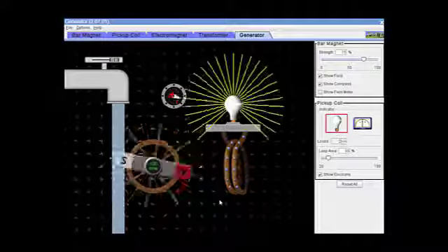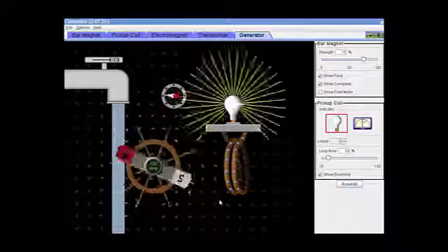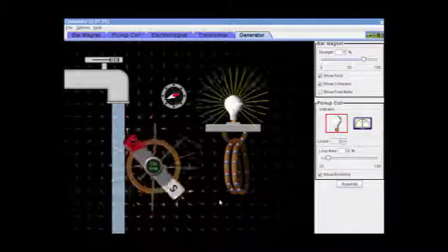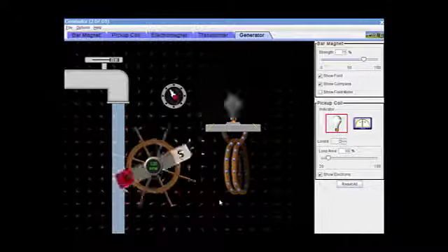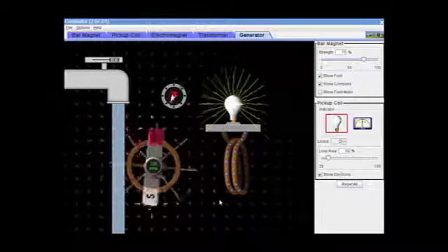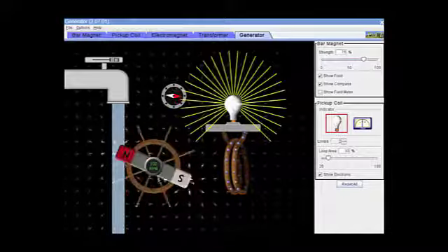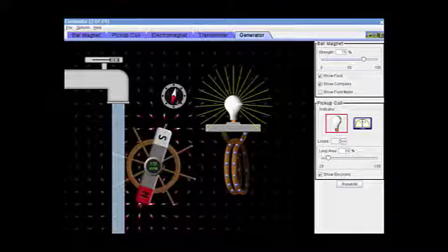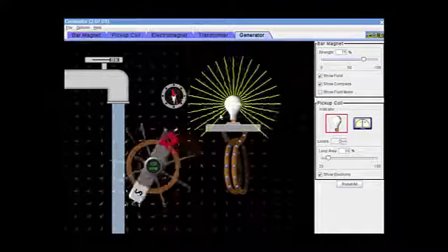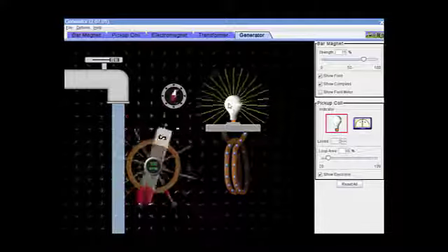So if you do the math, in order for a generator to turn to create this effect happening 60 times a second, it would have to turn 3,600 RPM. So at that speed, which is 36 times faster than what we're seeing here, at 3,600 RPM, you would not be able to notice this change in intensity. It would be happening so quickly that you wouldn't be able to detect it.